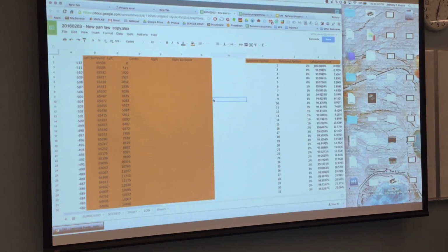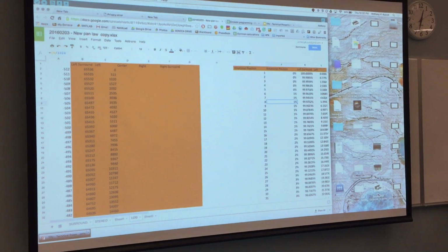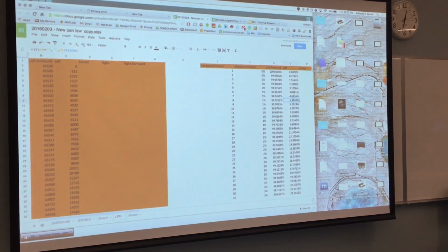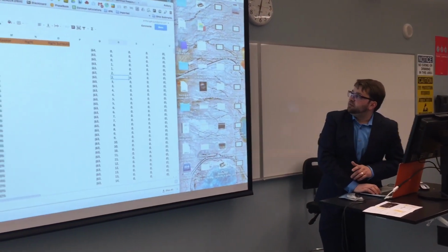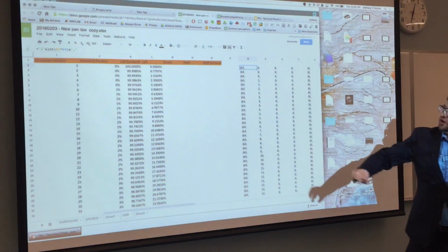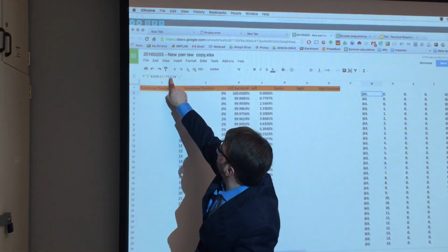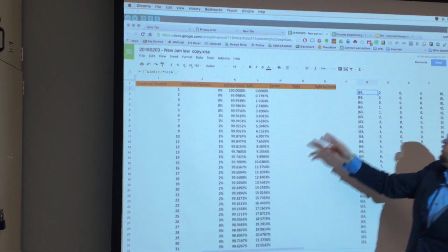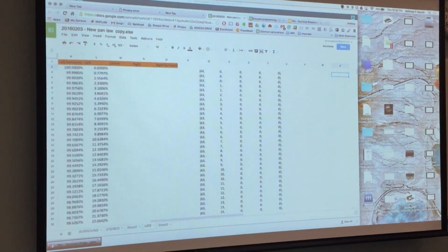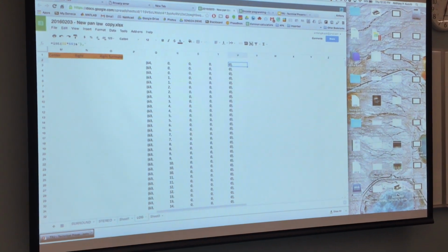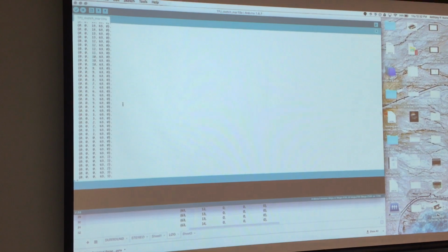So here I have the math for doing the rotational position. I created it in a percentage because a percentage is a really nice scalar. And then I made this formula, you can see, so I created an integer, K2, I take that percentage, multiply it by my range of 64, and poof, I get 64, and it generates all of my C code for me. So I just take this and I dump it into Arduino, and poof, there it is, there's my lookup.